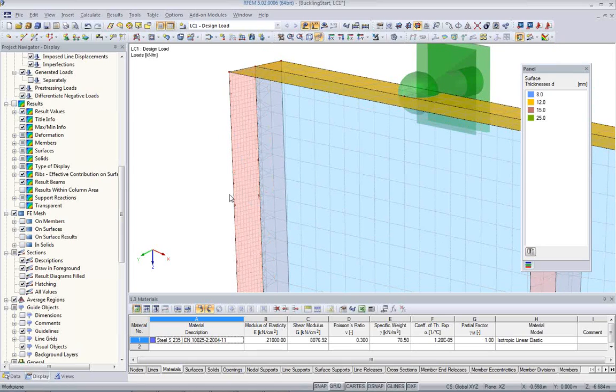This will create, of course, a longer calculation time, and you should think about whether you need a really fine mesh or whether maybe you can get by with a coarse mesh. This depends really on the structure. In general, we say you should have maybe 4 to 6 elements along such a surface of interest. If you don't really have detailed interest in the results, you maybe get by with a more coarse mesh.